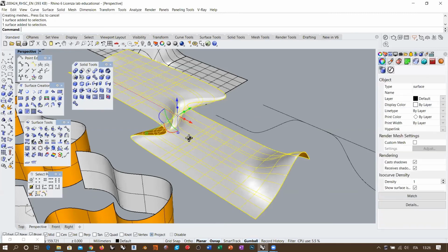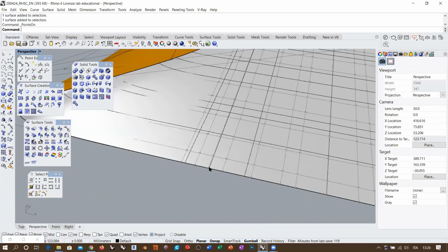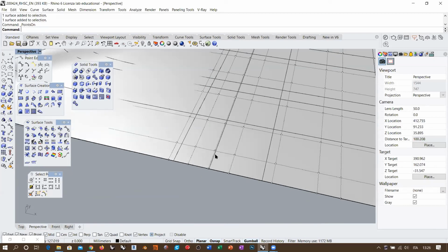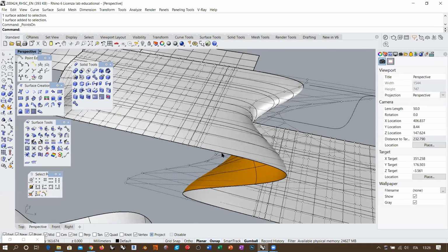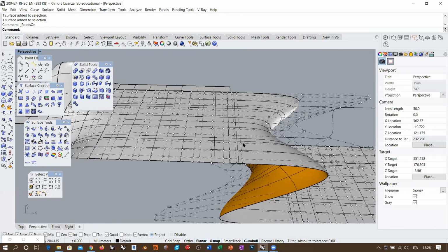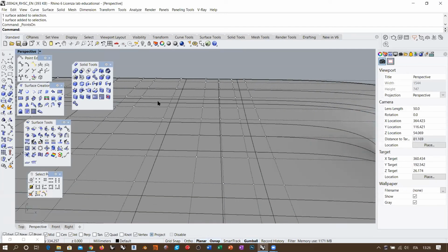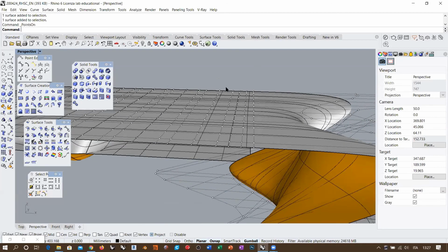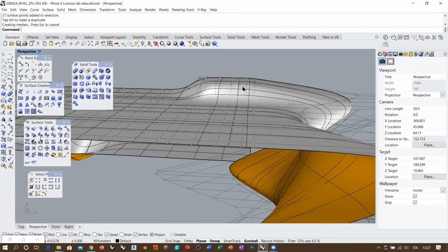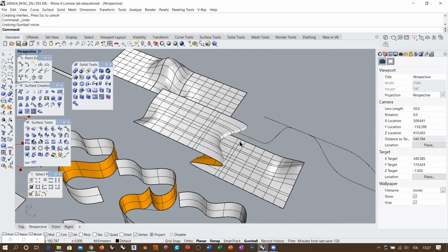And one consideration, we are merging, but if we take into account the topology, it's important to double check that you don't have control points coincident with the isocurves, because this will mean a kink. You see that merging creates a perfect smooth connection. That was what I was saying right now. So it means that you have no internal discontinuity along these surfaces once they are merged, okay? So it means that this is one unique surface flowing in these areas. Okay, it's very important. Okay, so it means that you completely lose the original objects.